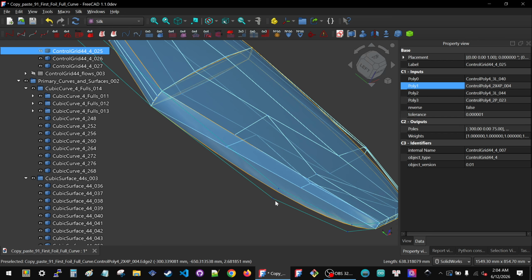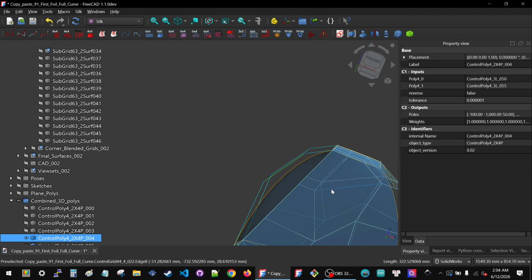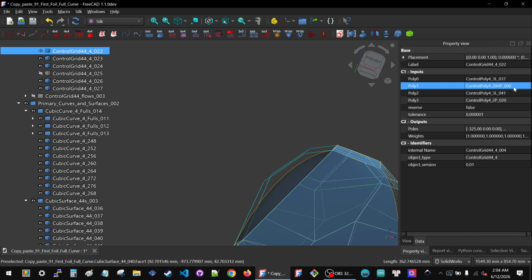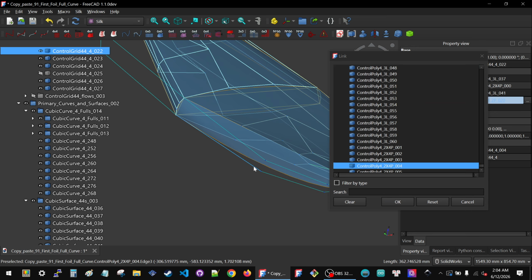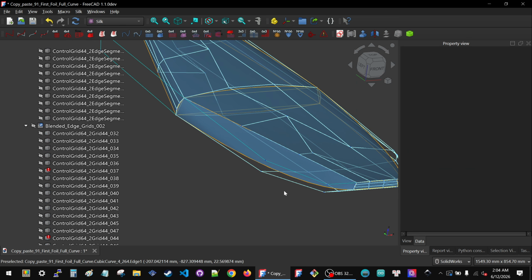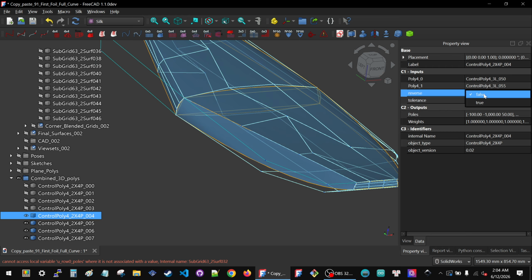But now I want to hide this grid so I can see this clearly, because now I need to adjust the underside face, and I'm swapping 20 with the lower one. Both sides are good, but I'm still getting errors. That means this poly is backwards compared to what the cutting points expect.